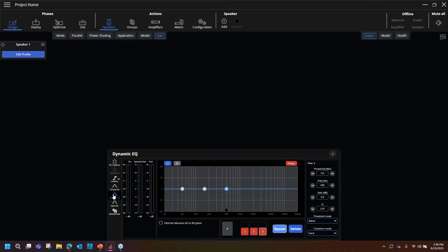Again, these are advanced functions that maybe you use to get rid of sibilance in a primarily voice system, but similar to the EQs I was showing for side chaining the crossover, these can be frequency dependent. Again, these are advanced topics. Be sure you know what you're doing. You could do a lot of damage if you're tinkering around in here and creating big boosts or cuts if you don't quite know what's going on.